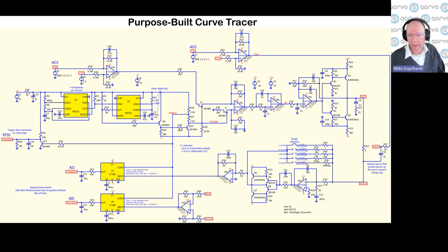And then I go through a 1, 2, 3, 4 pole Gaussian filter, to make it easier for my electrometer, my transimpedance amplifier, to keep this active ground at ground. So I filter it so it looks like a Gaussian pulse. Anyway, that's the circuit.